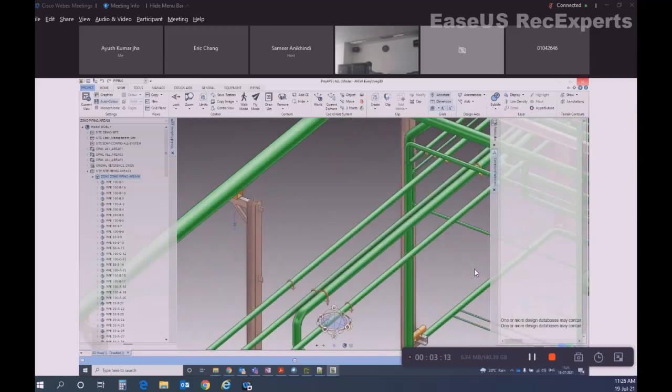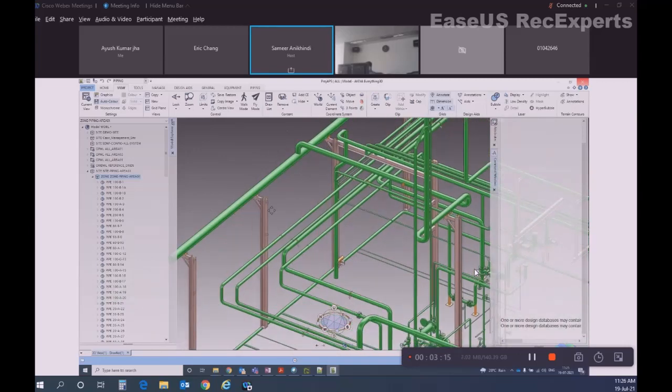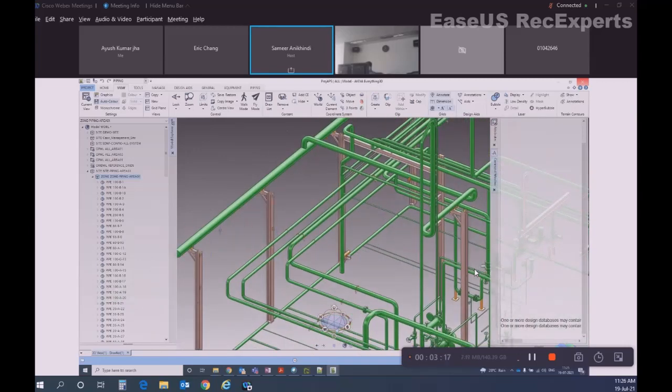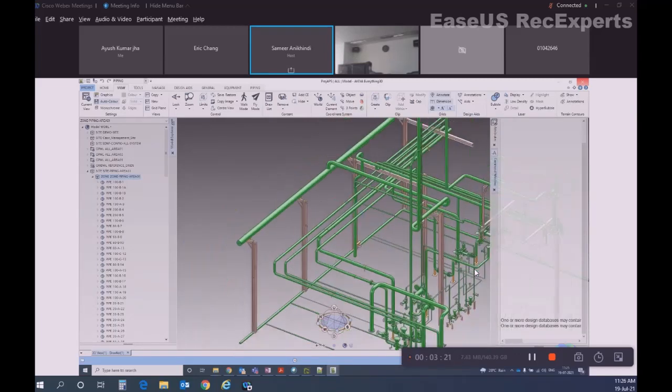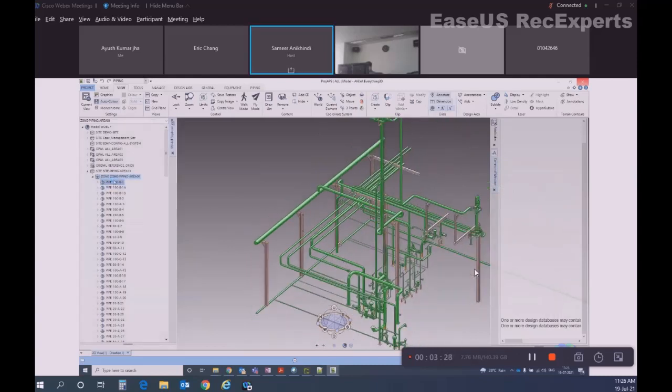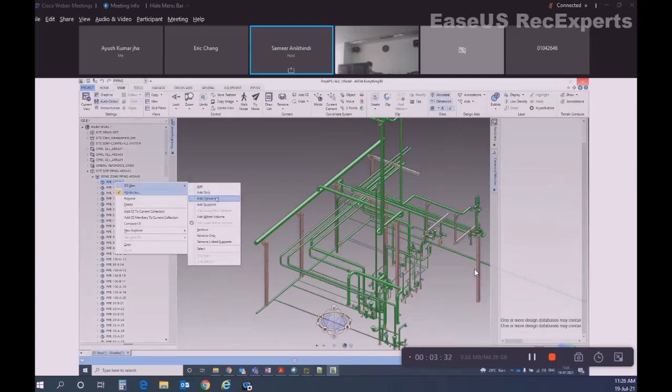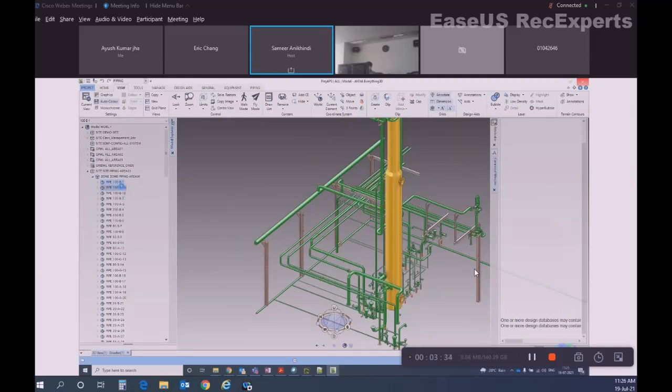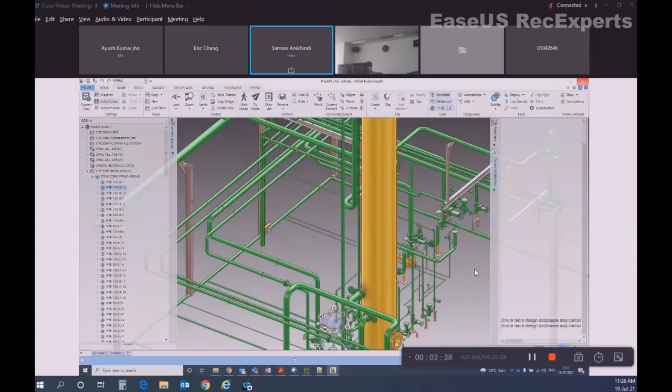Support is another thing which is connected to pipes. The support hierarchy is different than the pipe hierarchy, which we will discuss in support training. But if you set on click be on zone and add, it will add the connected support. But to add equipments, you have to go to individual pipes, right click, add connected. So on individual pipes, it will add the connected equipments.